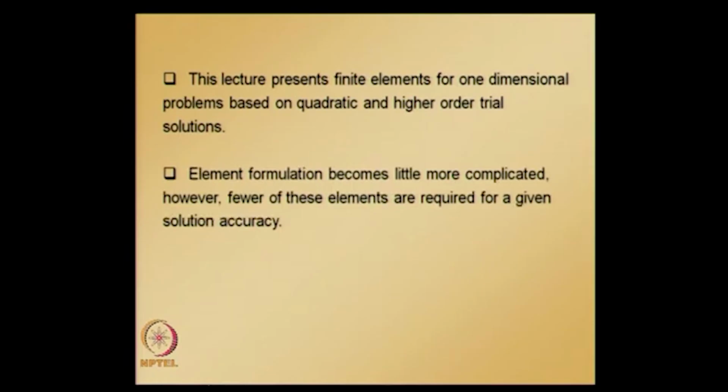when we use higher order elements, element formulation becomes a little bit more complicated. However, fewer of these elements are required for a given solution accuracy. So even though formulation is more complicated, we can use a smaller number of elements. So the size of equation system that we will be solving will be smaller than what we usually get using linear elements.